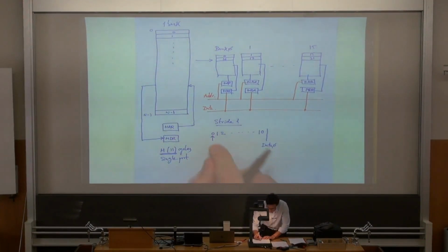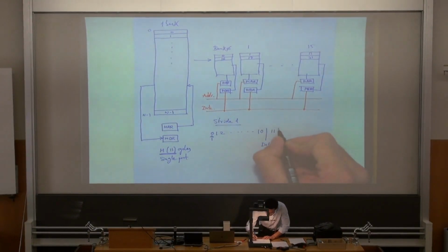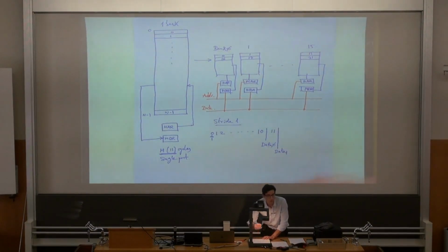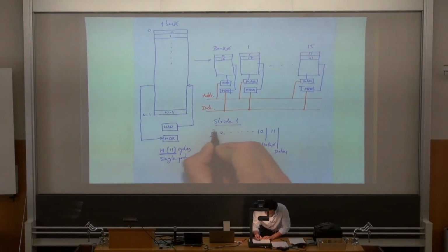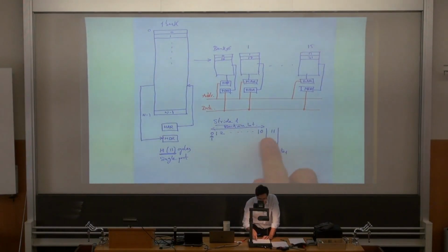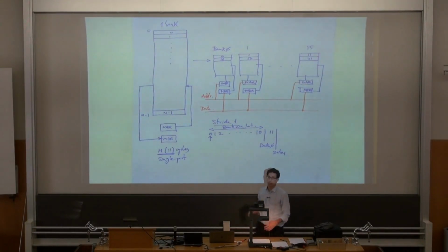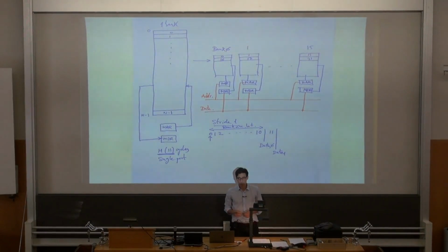And because in cycle 1 we started the access to bank 1, one cycle later we will have data 1, and then 2, 3, etc. Our bank access latency is still 11 cycles, but our throughput, or bandwidth, is 1 element every cycle, thanks to the use of the 16 banks. And this is how vector processors are able to access memory in a very efficient way.